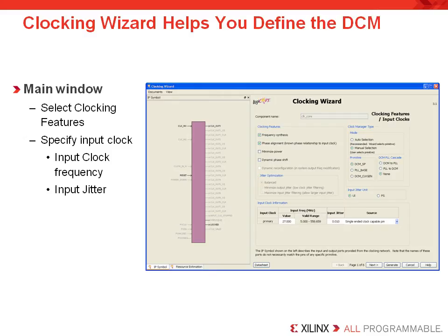The most common use of the architecture wizard is to customize clock managers. This is done using the clocking wizard present in the architecture wizard's IP core list. The clocking wizard is an interactive graphical user interface, or GUI, that creates a clocking network based on design-specific needs. The required clock network parameters are gathered in a linear manner, which allows you to select only the desired parameters. Using the wizard, experienced users can explicitly configure the chosen clocking primitive, while less experienced users can let the wizard automatically determine the optimal primitive and configuration, based on the features required for their individual clocking network.